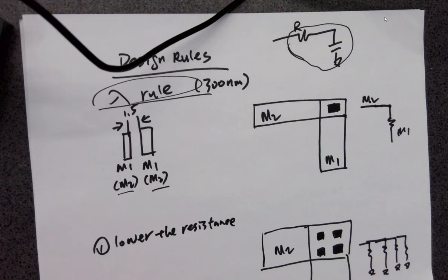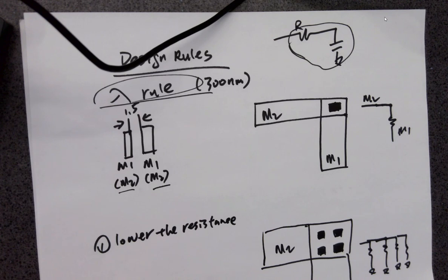For the default, I think that was 0.6. I forgot the dimension exactly, but for the default dimension for the traces in Eagle PCB, if you directly use it to route everything, you can find out there will be somewhere around 0.3 volts getting lifted from ground. You got a ground here, which is 0 volts, and over here, same ground, but it's getting like 0.3, 0.4 volts. Because of the resistance, it's causing a voltage drop.